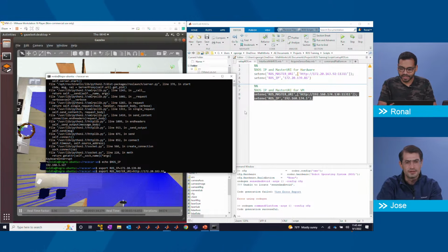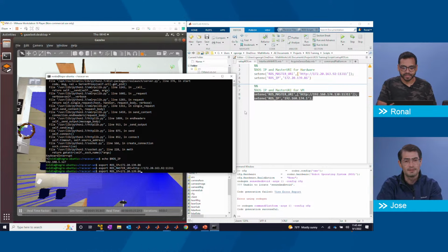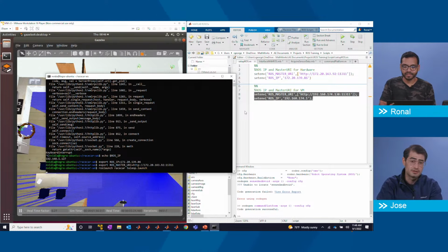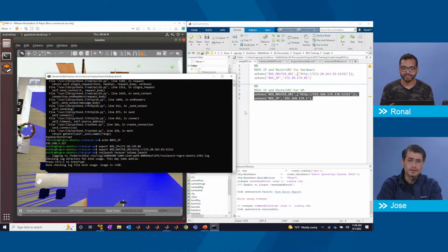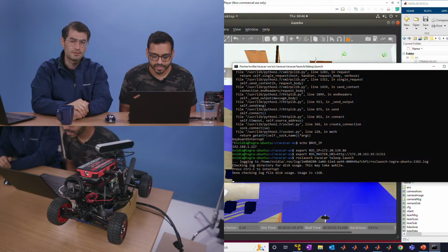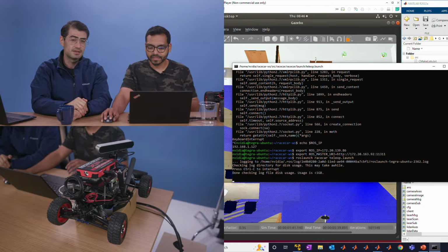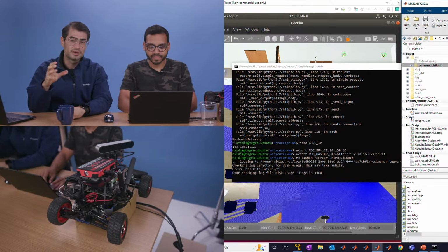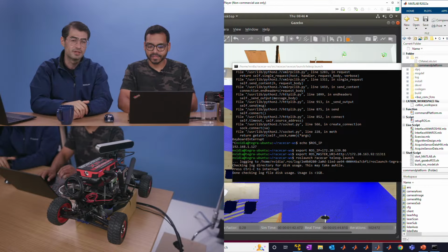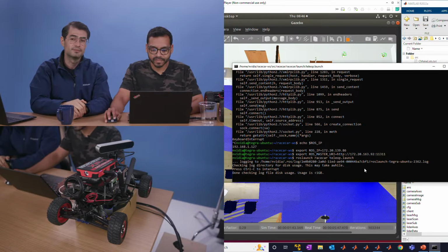We'll take a question. It says, can we extract sensor data, radar or LiDAR, from a MATLAB simulator? That's a great question. For instance, with this Gazebo simulator, we already showed you how to extract LiDAR data. There are other MATLAB-available simulators where you can actually do high fidelity sensor modeling. It basically means that you can tune all the parameters in there and also create what is called synthetic data. So you can get LiDAR scans simulated and then obtain that for further testing.